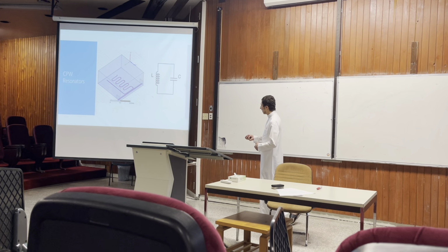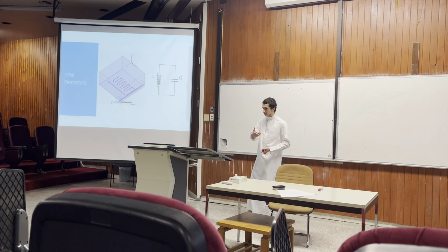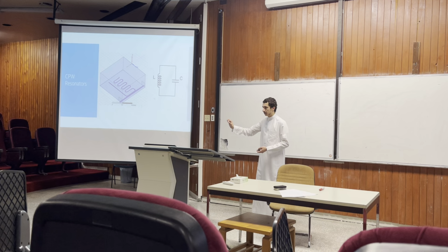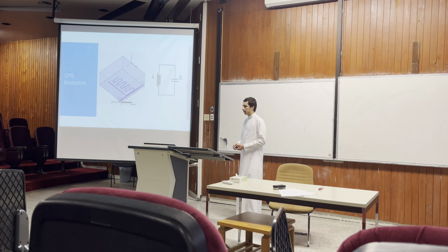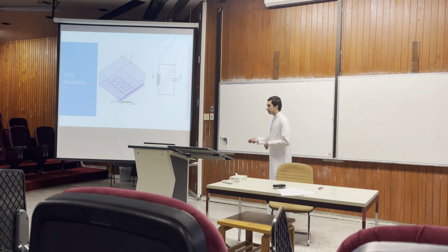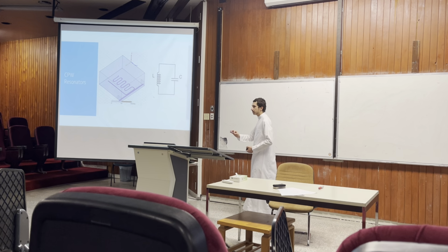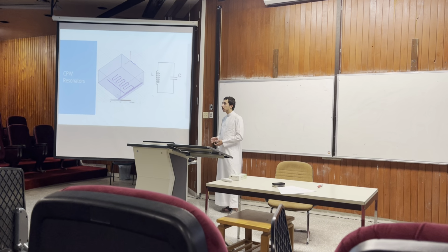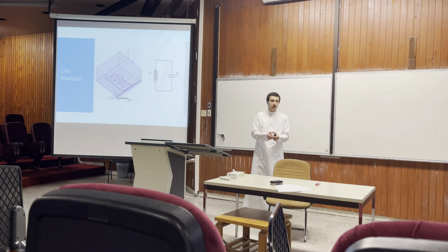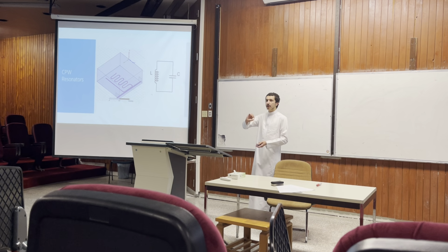Okay, so because we have inductors and capacitors as circuits in terms of our implementation of the qubit, each qubit has specific resonance frequencies that we can use to help identify our system. But when we try to measure this state, it doesn't really make sense to send one specific frequency, because sometimes the noise in the environment alters this resonance frequency. So for example, if you have a resonance frequency of theoretically 5 gigahertz, in practicality it might not be exactly 5 gigahertz, it might be slightly higher or slightly lower.